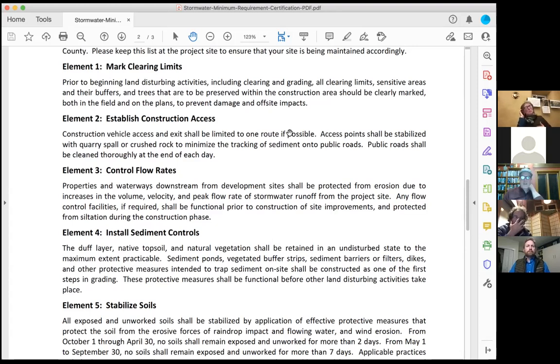It's really where planning is just crucial, so that initial marking, staking, flagging, defining where site access is going to be, where equipment is going to go, where people are going to park, is really important. And you want to make sure you've got all of your spill kits. You can just buy those spill kits. They have everything you need in case somebody spills gas or oil, and mark them first thing. Get your whole site set up.